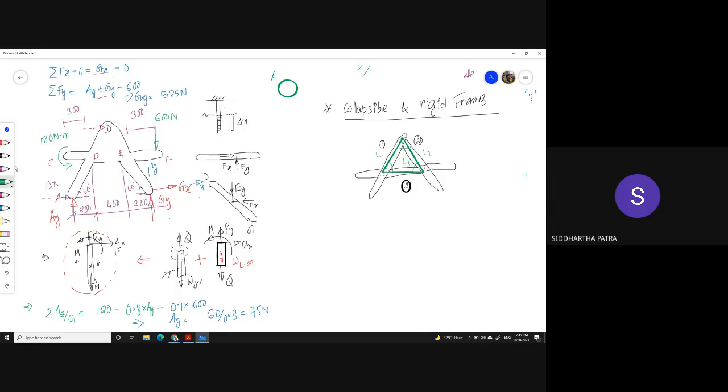You see, this is not very obvious. If I were to take 4 rigid bodies and pin them one after the other, I'm just drawing them as lines, and these are the pin joints. That is not a rigid structure, because to define a quadrilateral, not only do you need 4 link lengths, you also need one of the angles. And actually this makes up the 4-bar linkage, where by changing the angle of one of the links, you can also change the angle of the other side.